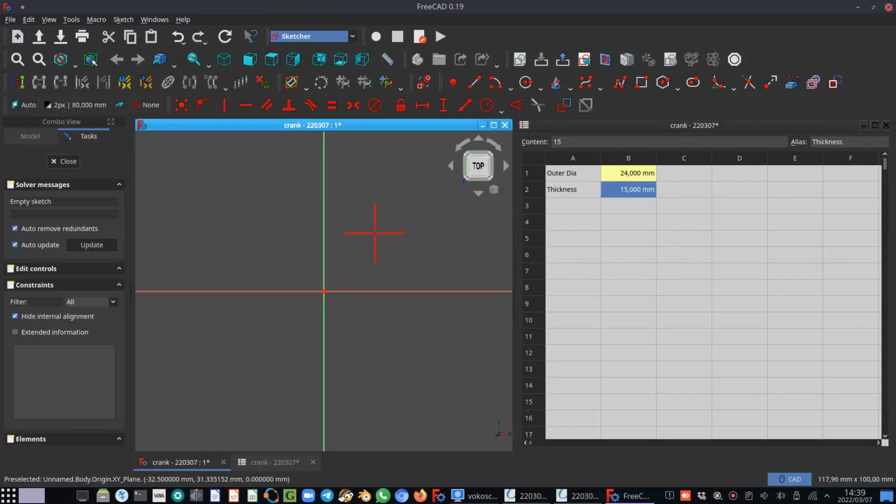Right, now for some reason the two windows changed sides, which is actually a good thing. It's not a problem. And you will notice that FreeCAD went into the Sketcher workbench because we are now going to create a sketch, which we've defined in the previous steps. So this sketch is very simple. We will create a circle by clicking on this white circle icon over here, and now we've got a choice of where we want to position the circle.